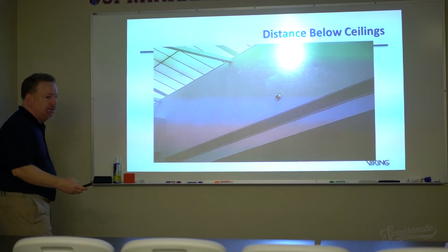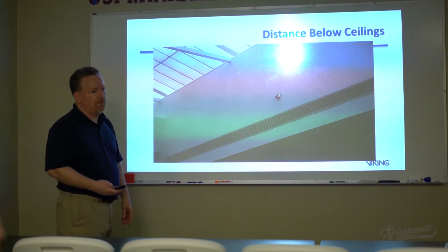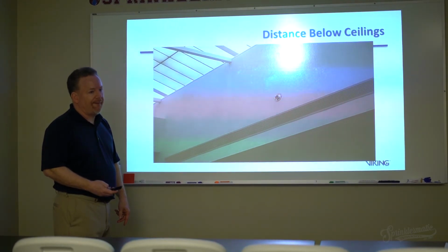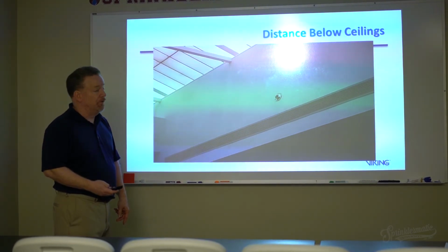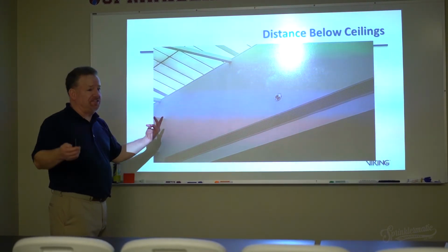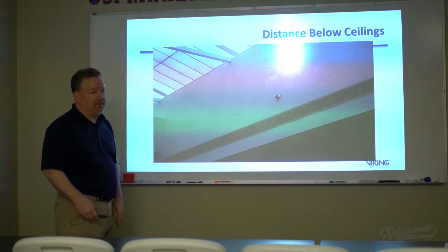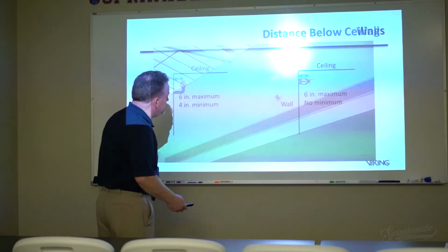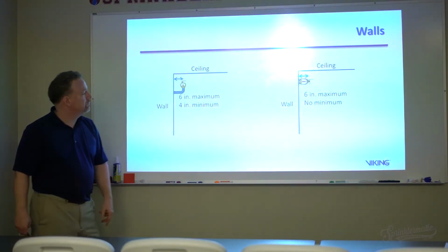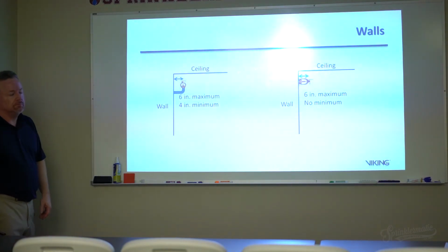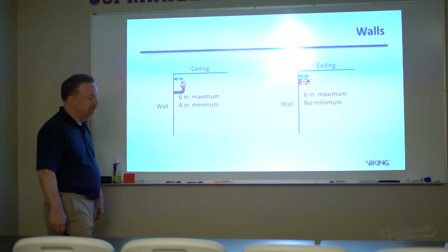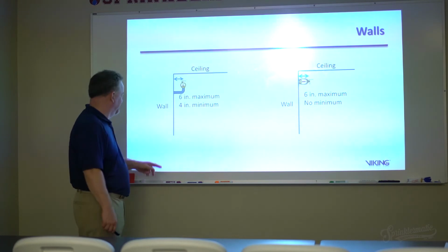We have a building that has an atrium. It has a deluge system at the 4th and 6th floor. They have sprinkler heads on a wall like that, but they're open deluge heads. In that case, the detection's going to send them running. Every month, the guys that clean the carpet in the rooms run it on the 2nd floor, come up and hit the infrared beam. They set that off several times.